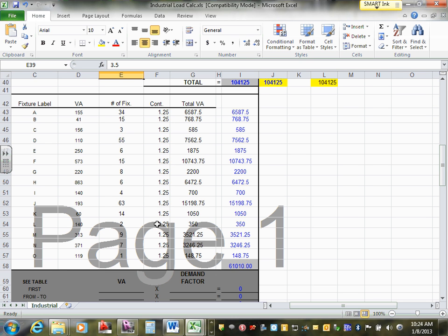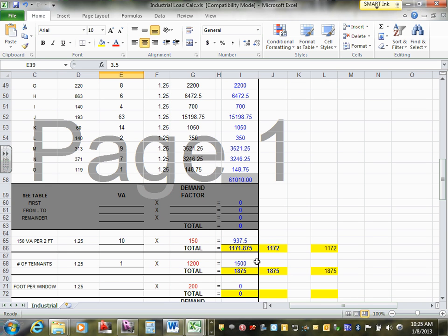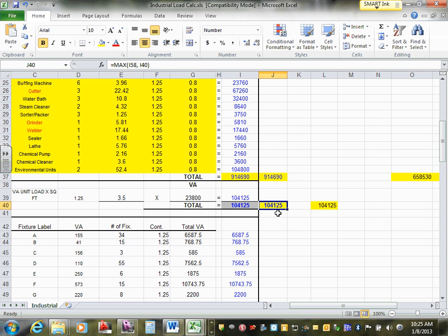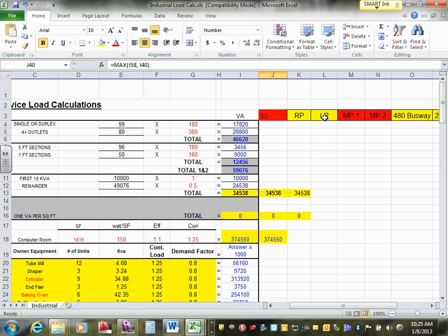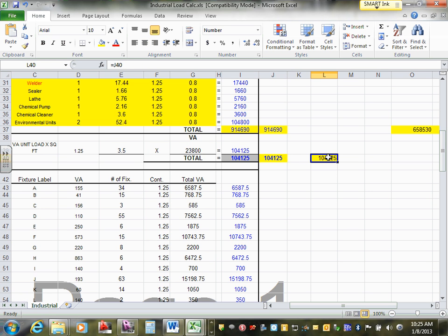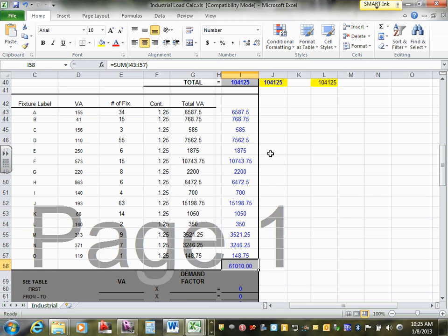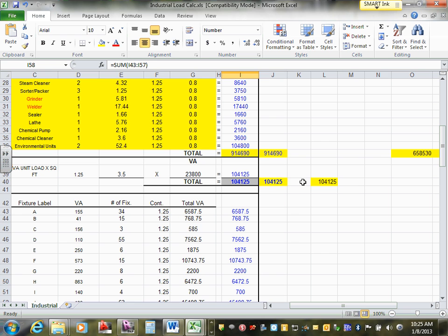That's the actual load. So you take the 3.5 load and the actual load. And what do you do when you have two numbers? Which number are you going to pick? The largest. And that's what we did. So I get 104. Can you guys see that 104? That's from the code, and I put the 104 under lighting. Why do you think it went under lighting? Because it's lighting load. And the actual load happened to be much less, 61. The actual load is 61, and the calculated load is 104.